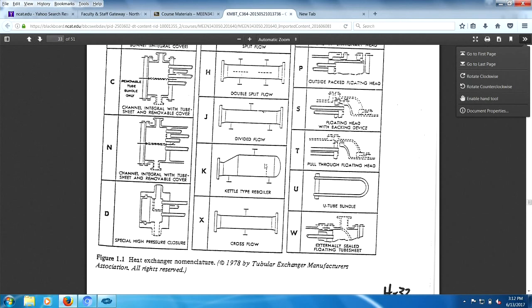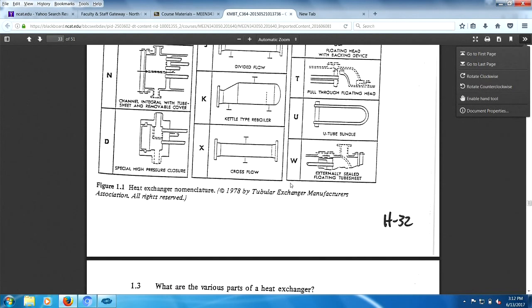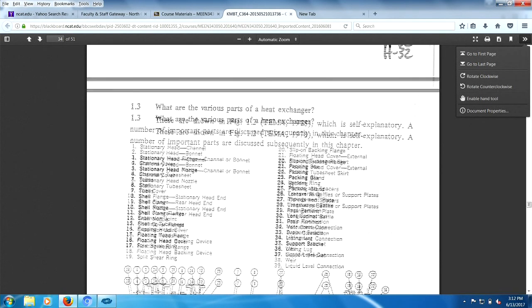Which for a reboiler wouldn't be a bad idea. U-tube, see that? There's no return bend there. Problem with U-tubes is bending the tubes such that they're not crimped. You ever try to bend a tube? It can be, how can I put it, quite humiliating if you... Yeah, give that to your children to see if they can do.